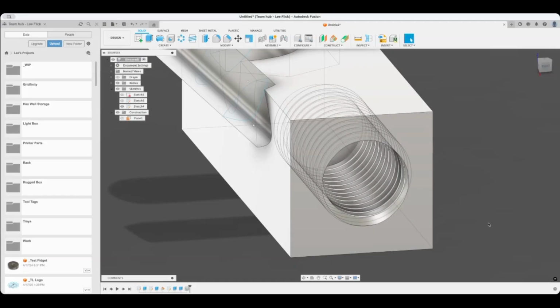The thing you've got to watch is, depending on the plastic, this is going to shrink some, and your bolt may grow some. So a lot of times, if it's a steel bolt you're putting in there, you might have to increase the model a couple percent. There's a whole way of doing it. It's kind of a complicated thing.